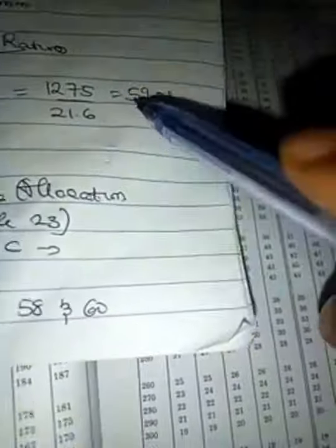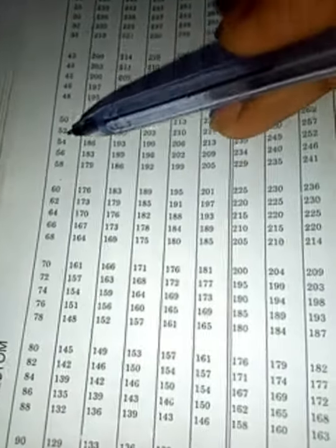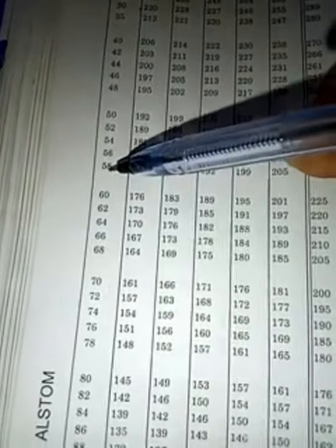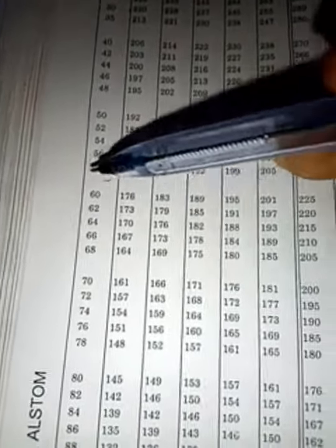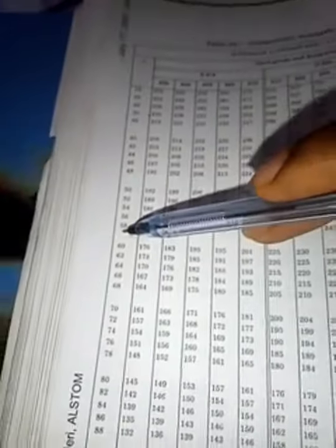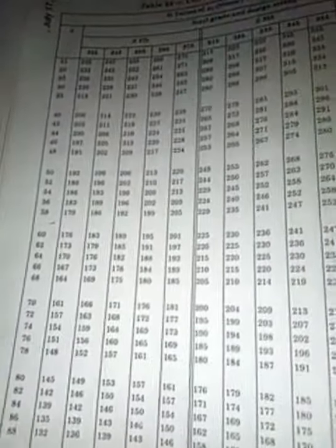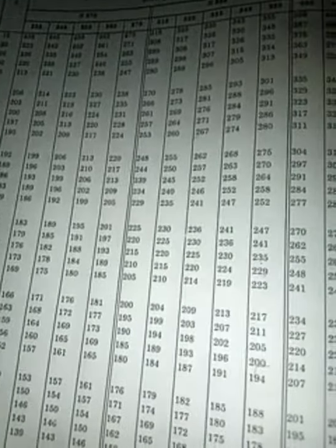So you go to your table. This table is still saying A, and this table is saying C. You can see that in this table, there are different values of lambda. So in our question, what was our slenderness ratio again? Our lambda was 59.08. So you search for 59.08. We can't see it. We are seeing between 58 and 60. That means we have to interpolate. 58 and 60. What are you looking for? You are looking for S355. Where is S355? Here.